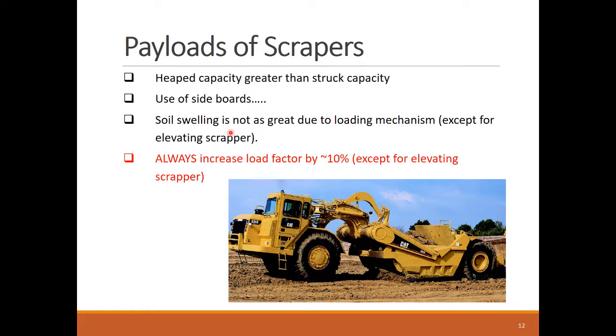As the scraper cuts through the soil, the new soil entering the bowl compacts the soil already in there. So realistic payload estimates require increasing the load factor by about 10%. This assumption doesn't apply to a type of scraper called elevating scrapers, which we'll see later in this lesson.